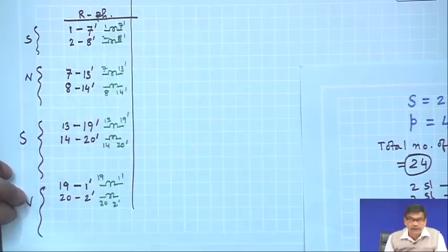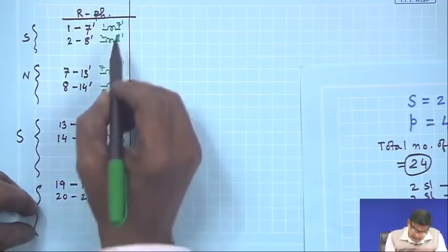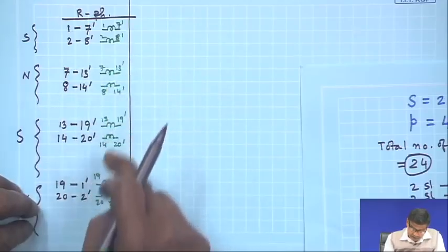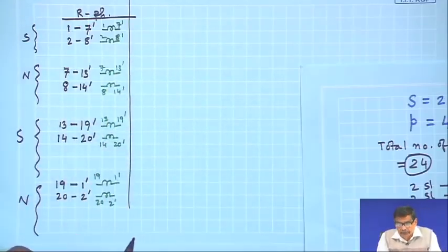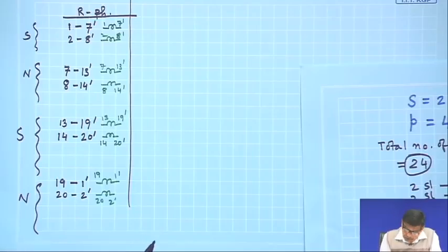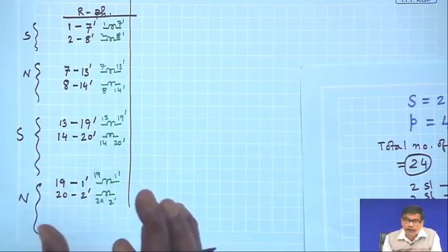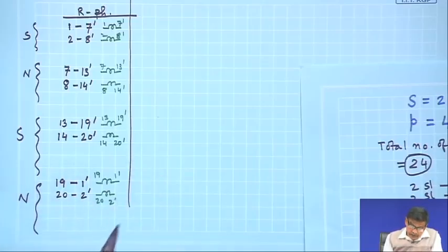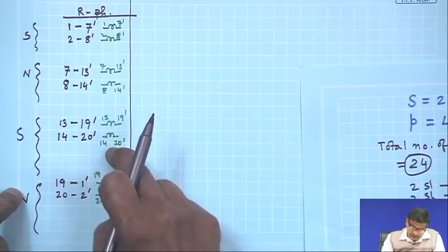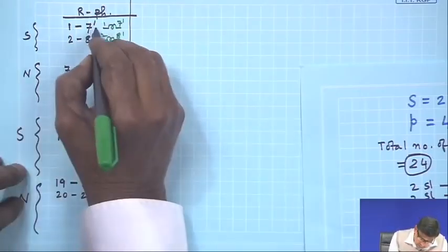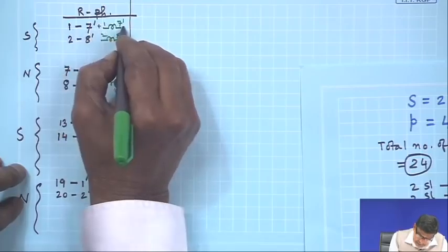So, all the 8 coils have been drawn and these two I will connect in series, get one group, another group, another group, another group. So, if you decide that you will distribute these slots such that under one pole it is equally divided among the phases, that is each phase will occupy 60 degree, then the number of groups of coils that will be available will be equal to the number of poles. And let us assume also that suppose this is plus, this is minus.